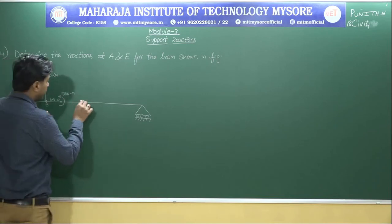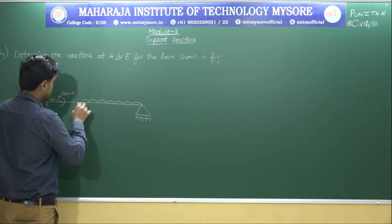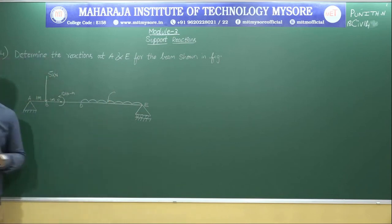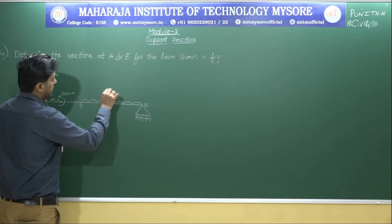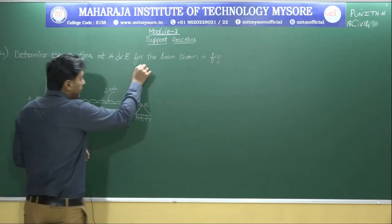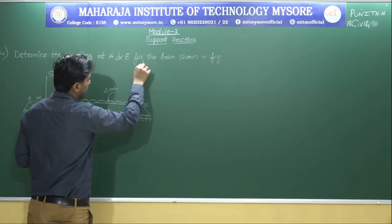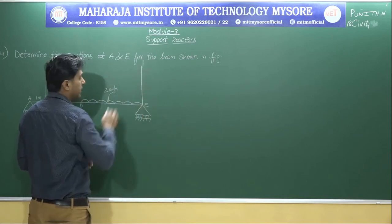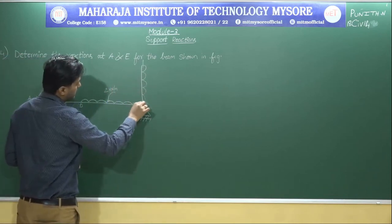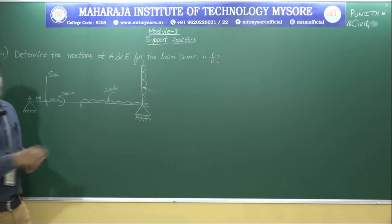Next, after leaving 1 more meter span, there is a continuous UDL like this. So this is D, this is E portion. So the UDL that they have given is 2 kilonewton per meter. But here the twist is, they have given one more beam in this particular direction. Here also the UDL is acting, and that particular distance is, so 3 kilonewton per meter.